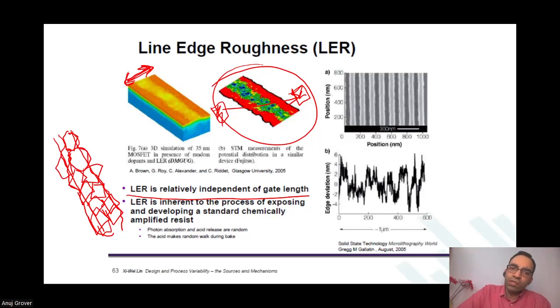Now let us come to 20 nanometer technology. At the lower technology node, it will be significant. The impact is much more. The difference is now around 15%. Means, sir, this LER will be the same across every channel length, but it will be more significant in lower technology nodes. Not just lower technology nodes, in the same technology node, if you use minimum length, the impact is more.